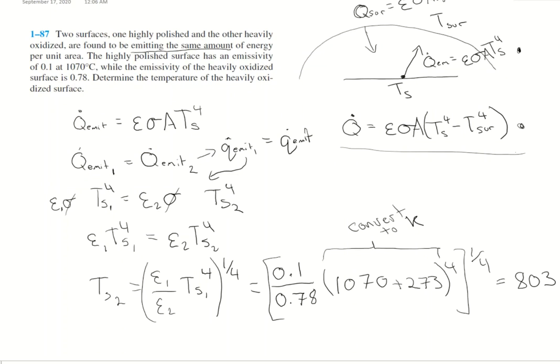If we're sitting by a campfire, the difference is very, very large, and so we'll notice it. But in buildings, we don't always perceive it, though it is actually very important. One example is large windows. Even if the air temperature is warm, you may feel cold just because you're losing heat to that window through radiation, if it's a cold day.